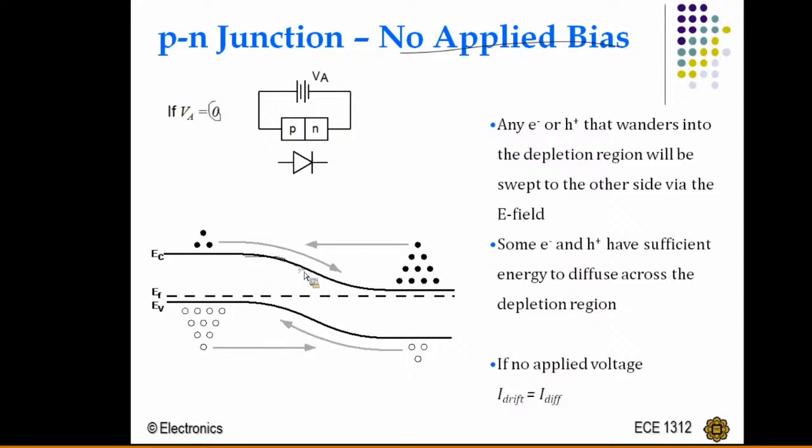So this is the case. Here there is a barrier. Due to this barrier, this electron directly cannot enter the p side. Now we have to reduce the height of this barrier. If you reduce the height of this barrier, then these electrons and holes can move very freely.